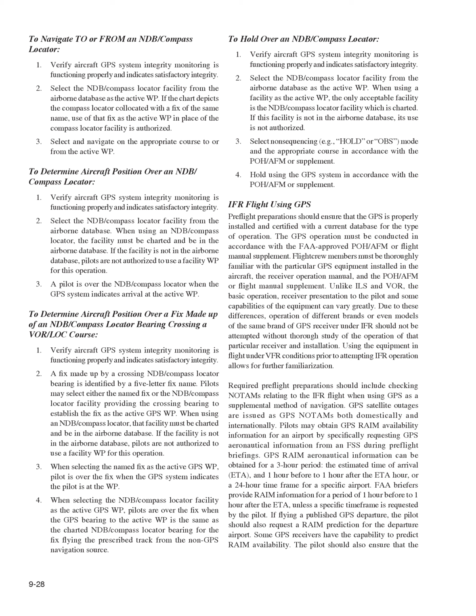The GPS operation must be conducted in accordance with the FAA-approved PO/AFM or flight manual supplement. Flight crew members must be thoroughly familiar with the particular GPS equipment installed in the aircraft, the receiver operation manual, and the PO/AFM or flight manual supplement.